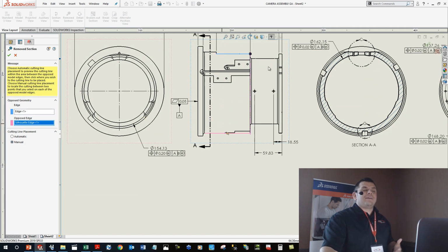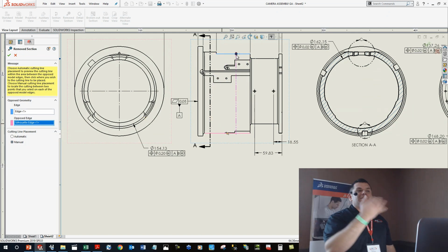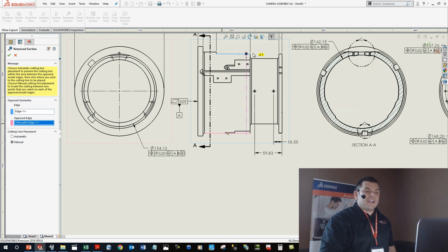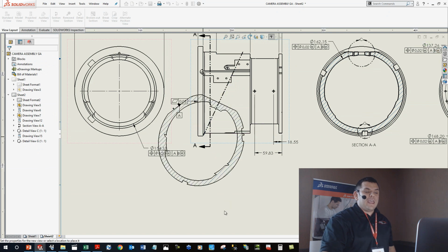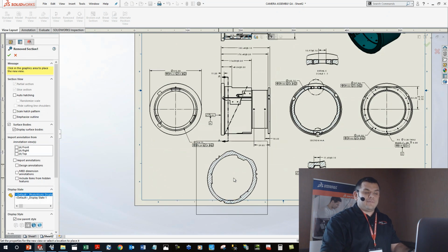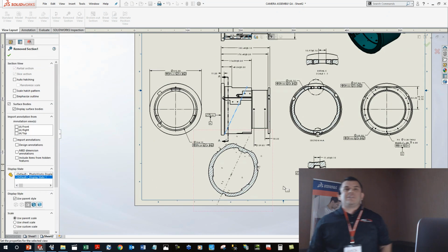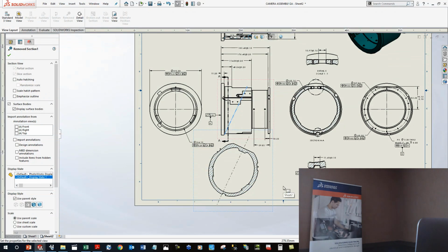And then instead of creating a bunch of reference geometry to control this section, you can now come in here and snap to, say, there, and maybe I want to snap this to the endpoint. And in real time, without doing anything fancy, I now have a slice section. So we've made creating slice sections even faster and more efficient than ever before.